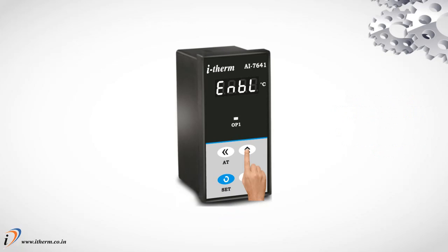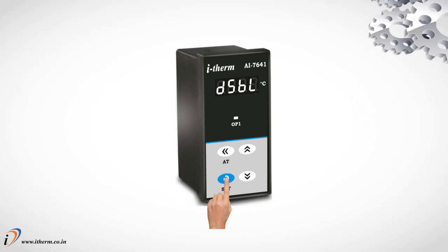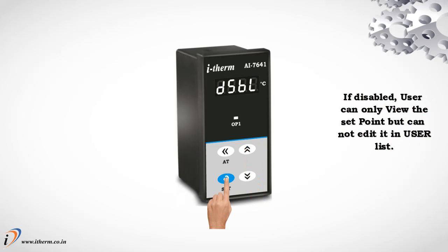Parameter 11, set point. If enabled, the user can view and edit the set point in the user list. If disabled, the user can only view the set point but cannot edit it in the user list.